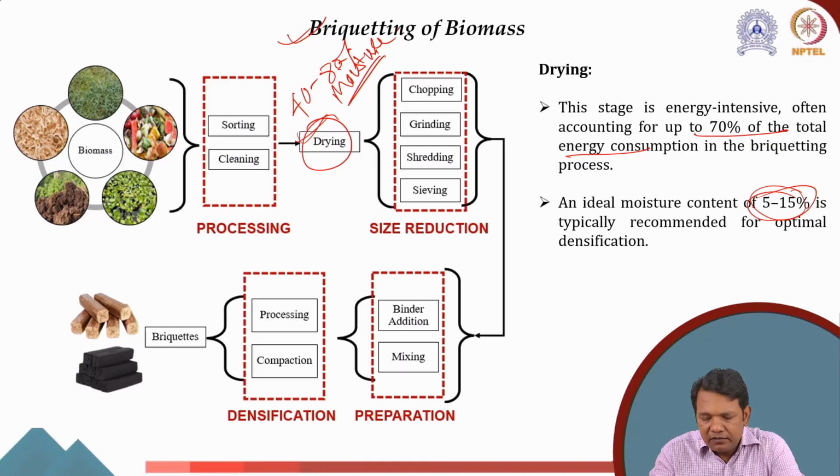Now after this we go to size reduction. However, you can also do size reduction prior to drying. Either way, it depends on an economic trade-off; we will have to see where we are making more profit. So that is again a detailed engineering part. But it's not necessary that you will have size reduction only after drying. You can have first size reduction, then drying. But one thing remains fixed, that you need both drying as well as size reduction units.